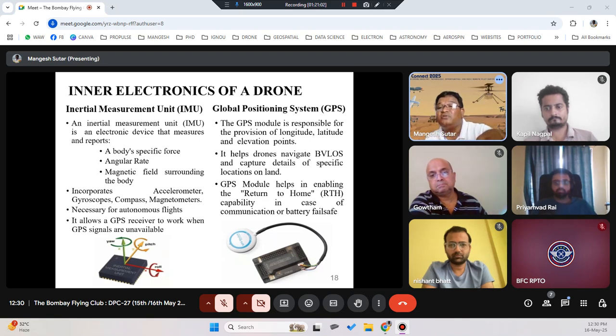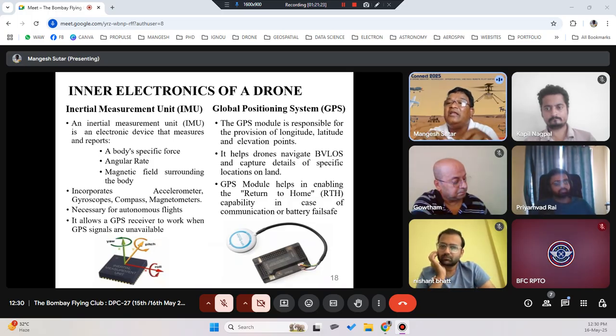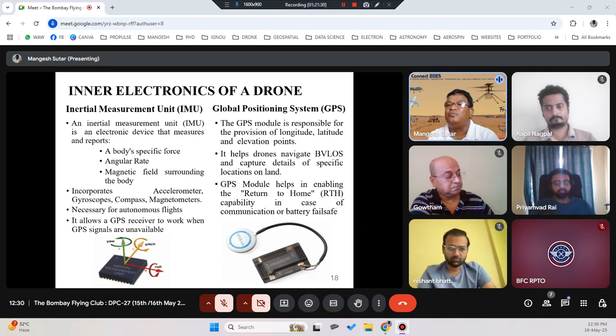Whereas my home location was where I got my drone ready when my battery was connected the first time, because I was calibrating or configuring my drone. So your home location and RTL location can be different, but they can be the same also. For example, instead of powering my drone at the home location, I can take my drone directly to the launch location, keep it there, configure it there itself, and fly it from there. So my home and launch location are the same now.